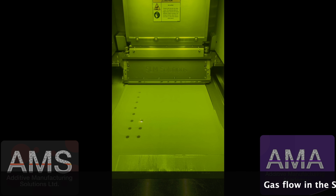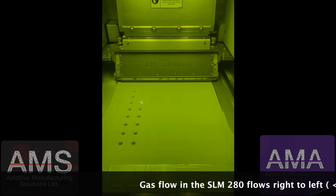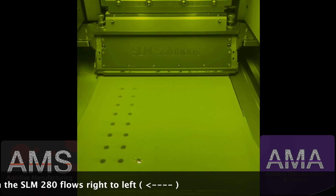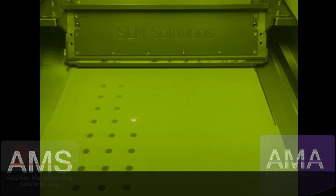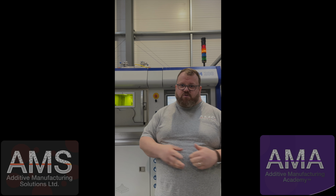across the bed. And what we're really trying to do is remove spatter and other fumes that come from this micro welding process. The gas flow will keep all of the atmosphere inert and will stop any oxygen absorption into the melt. That allows us to have really tight control of the mechanical properties of our end part, and it is a key factor that makes laser powder bed fusion a high precision, high performing technology.